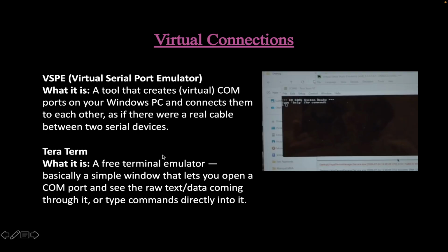Next is Teraterm. Teraterm is where you get the data, where you can see the system is ready. VSP is where you establish the connection between Windows and this Teraterm. That is where you assign which COM port you need for the project.